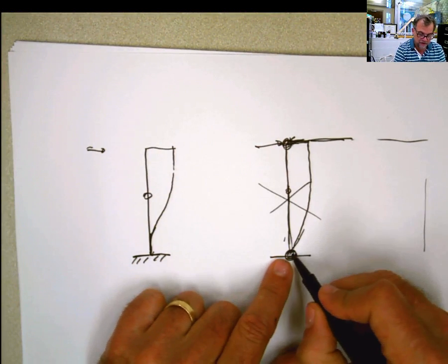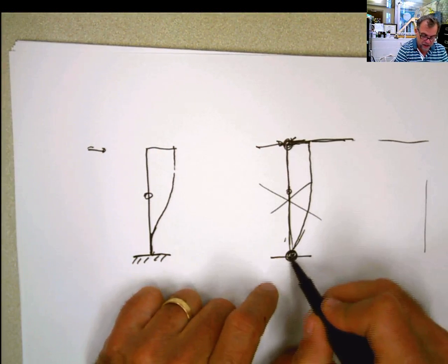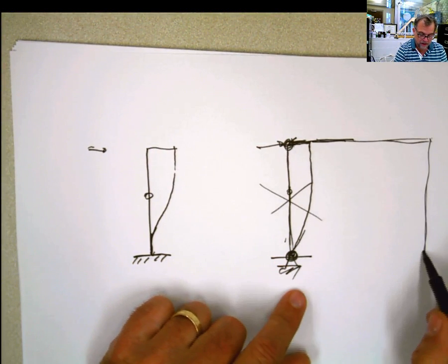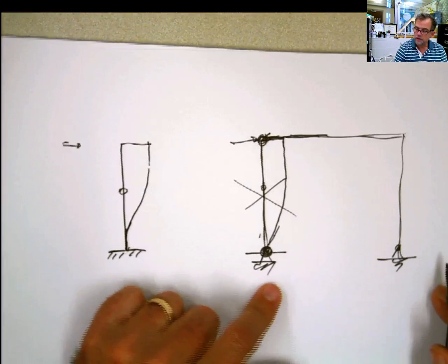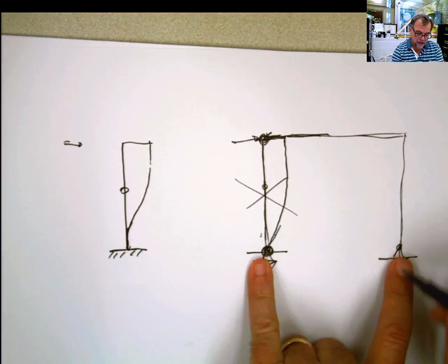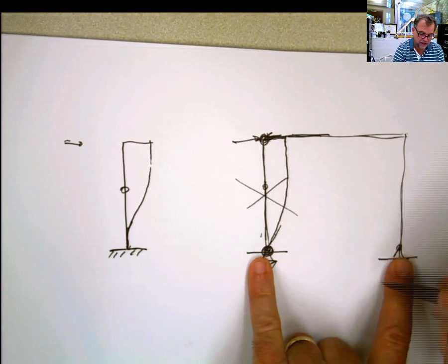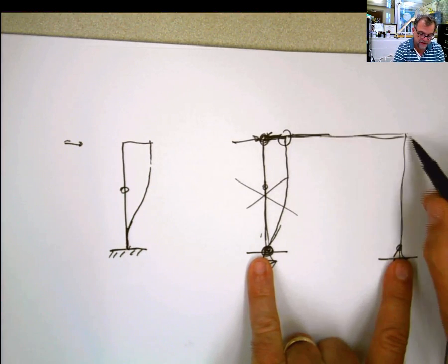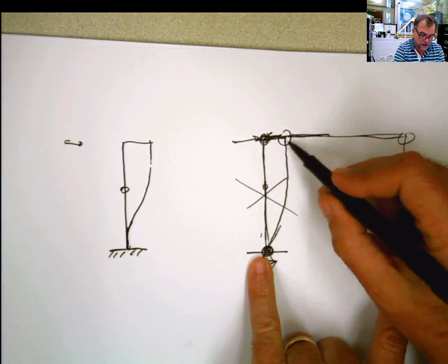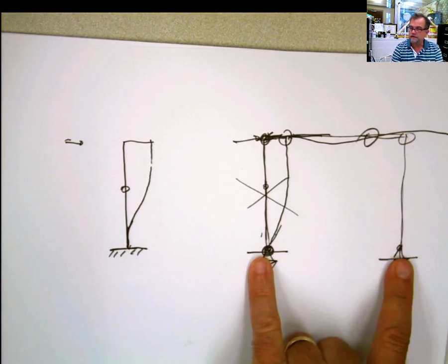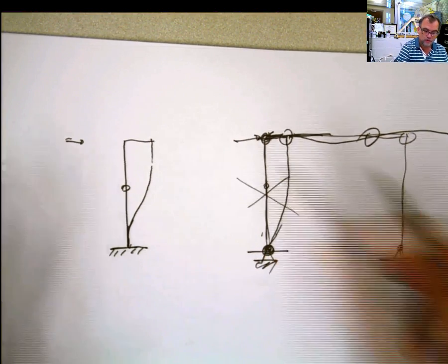But if I have this hinge here, or this pin here, and another pin here, which is the previous example that we did, at these points I don't have any indeterminacy, to say it that way. But this part behaves like fixed. So these two parts are gonna do that, and I'm gonna have the inflection point there. So this is what you have to check.